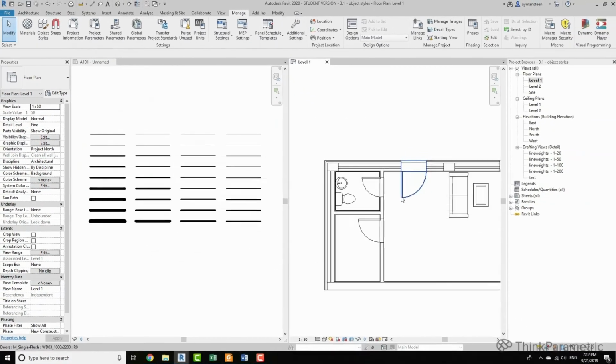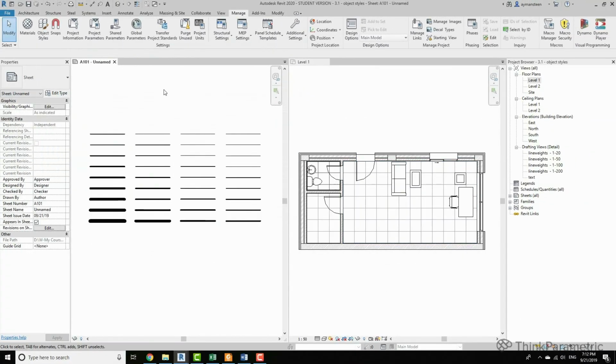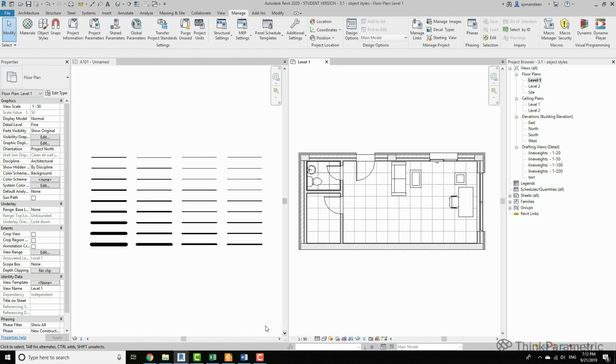So the general rule is that panel line weights are less than mullions, mullions less than external finish, substrate and structure, and furniture can be near the glass or mullion line weight, and tiles and hatches should be the thinnest. All tags and annotations should be kept at a minimum thickness as well. Finally, projection is less in general than cut, and it should be almost unified for most of the elements.